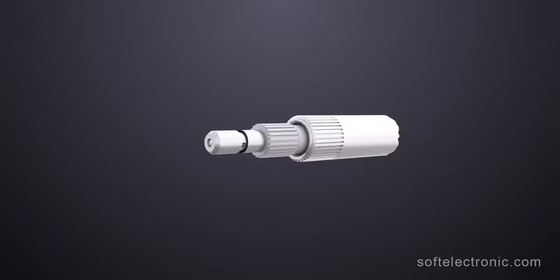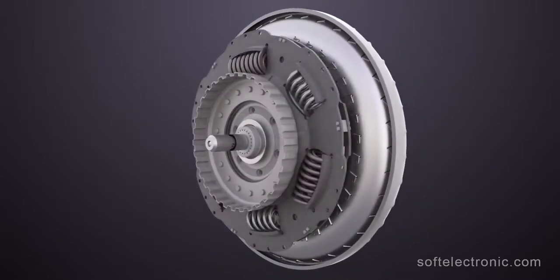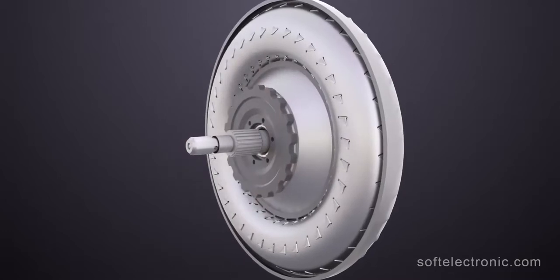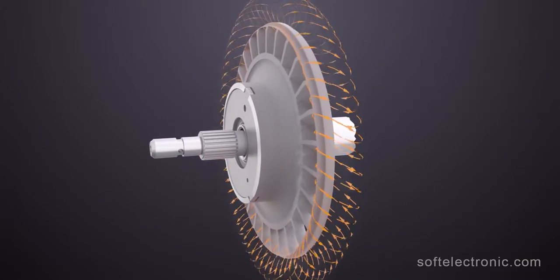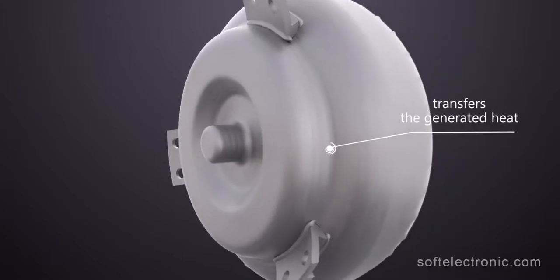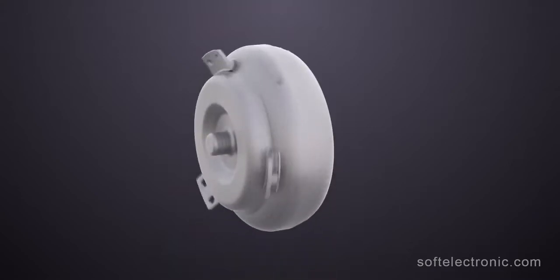The transmission oil enters the torque converter through openings at certain points on the different shafts of the gearbox. It has three main functions. It participates in the hydraulic control of the torque converter by pressure regulated from the mechatronic. It provides the necessary lubrication of moving components. It transfers the generated heat from the torque converter to the cooling system. In modern torque converters, there are two modes of operation.